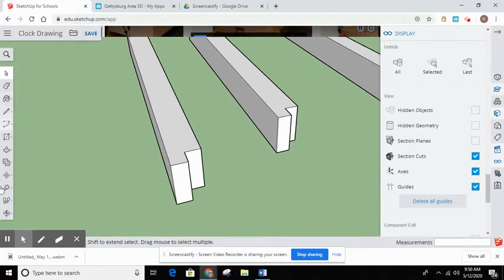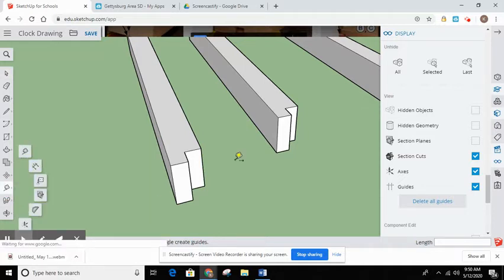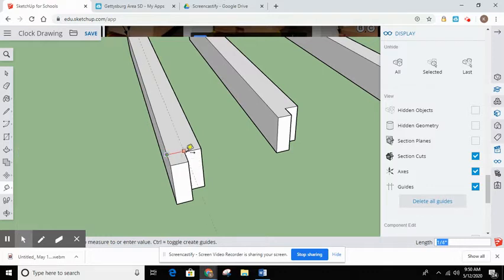And here's what I'm going to do. Here's how I'm going to lay this out. There's multiple ways of doing this. Here's where I want this to run. I'm going to come to this edge here. This is going to be my show side. And what I'm going to do is click, and notice that is 1/4. I'm going to put that mark right there. Then I'm going to come off of that mark and make another guide. And that one's going to be at 1/8 right there. So that groove is going to fall right in that position.